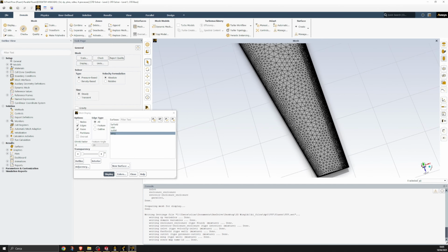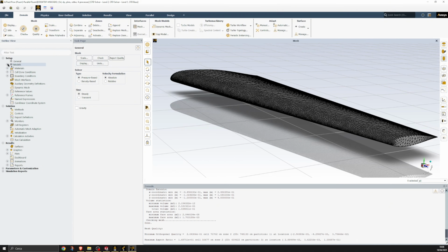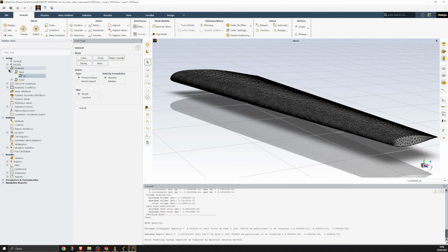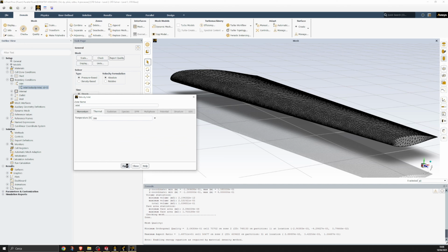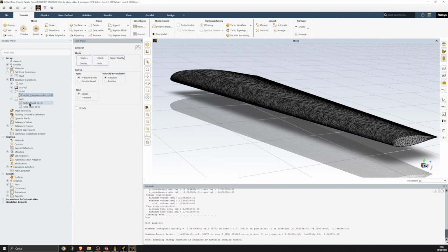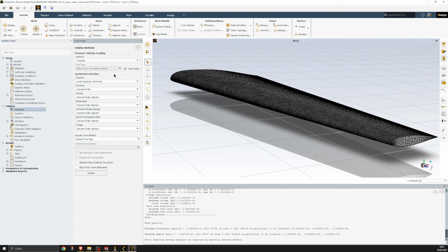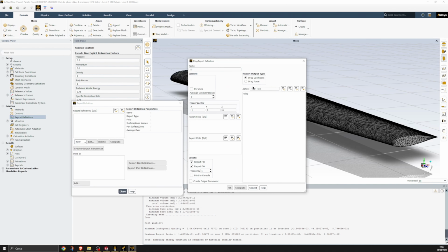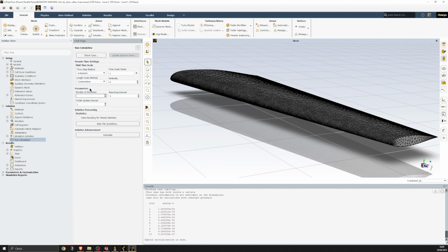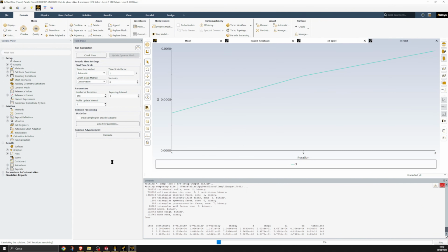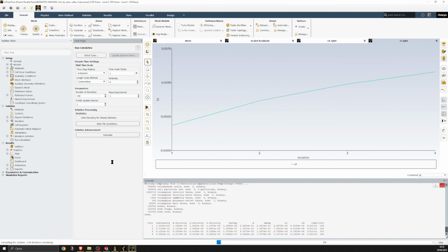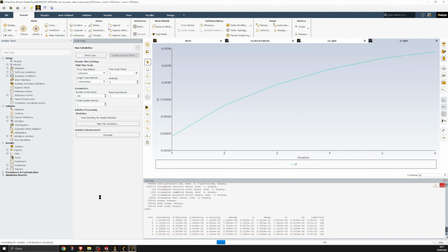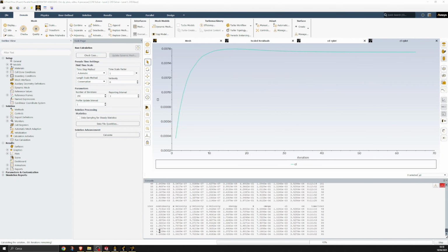After that we go into Fluent itself, and you can see the mesh around the surface of the wing. In Fluent, you have to select everything about the simulation. So from boundary conditions, turbulence model, everything. The temperature, the velocity of the flow, everything. And when you're comfortable with that, you can select the number of iterations of your simulation and check for the CL, CD, the residuals, and after that, your simulation should converge.